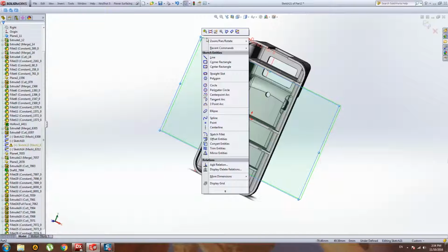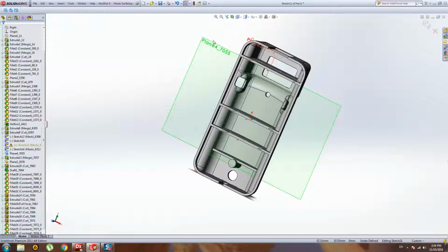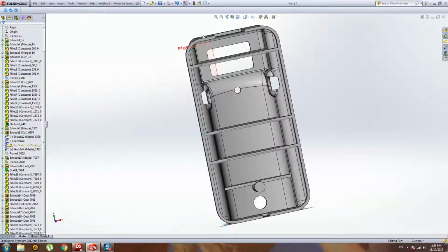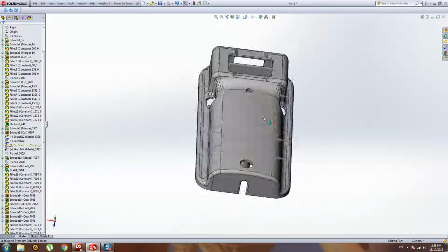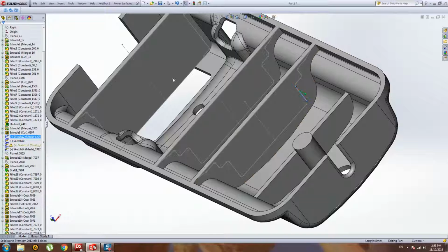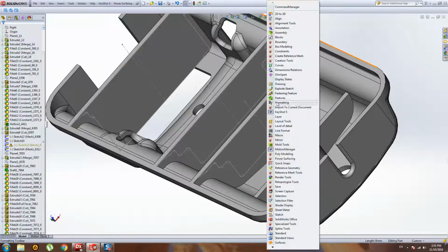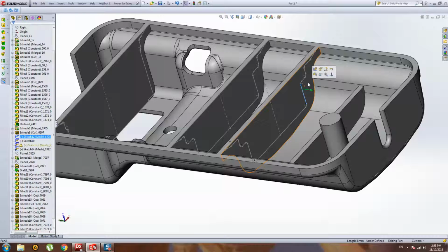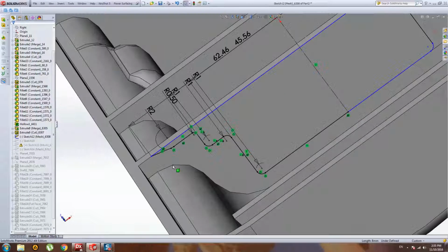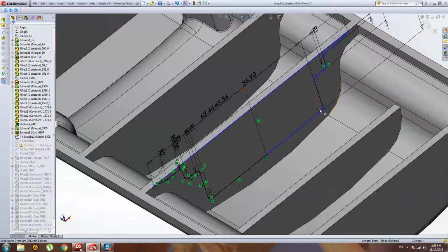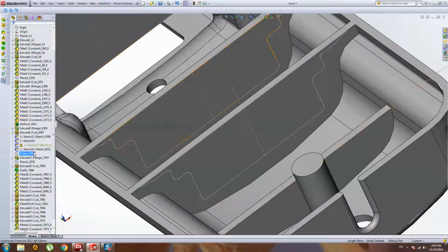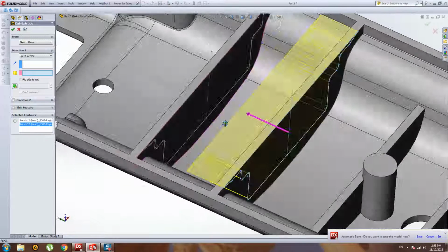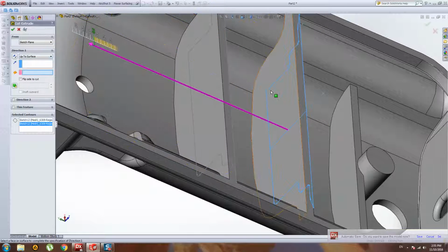Now let's hide some elements there. We see an unfinished process. Yes, I understand what happened. The system cannot make an extrude because I think this sketch is not fully closed. I try to select contours, yeah, and extrude it to next surface. Sorry, up to surface. Yeah.